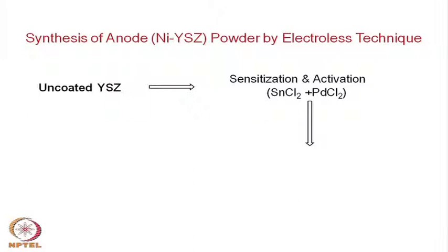So, every YSZ particle is coated with nickel, and whenever such nickel coated YSZ powders are pressed together or tape cast, whatever the fabrication technique, the nickel to nickel contacts will be ensured.